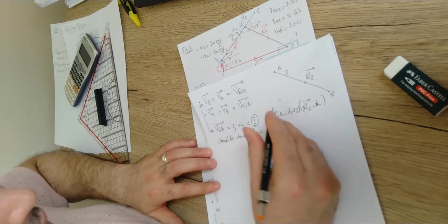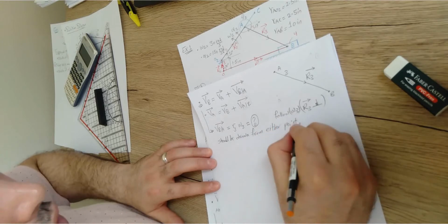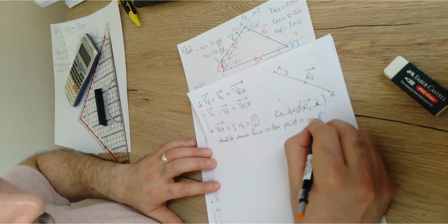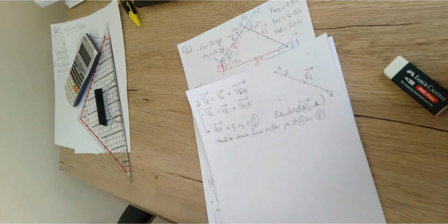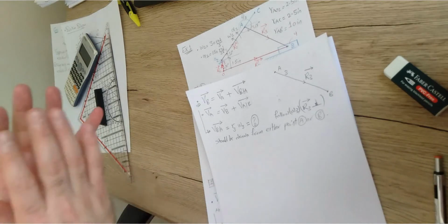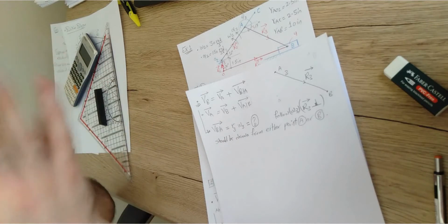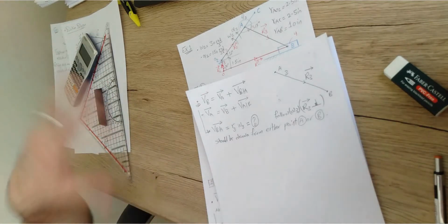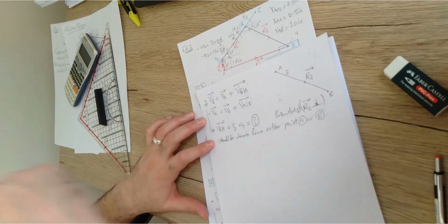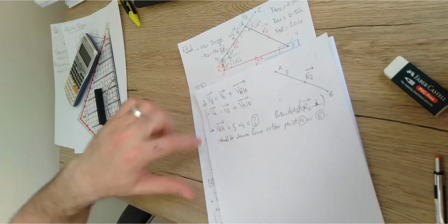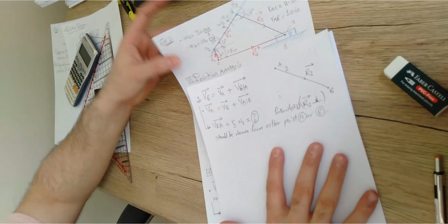Also, you should understand that this one should be drawn from either point A or point B, depending on which one of these 2 points will be located first in the velocity diagram. As I said, we start from the link that is fully defined, where the velocity information is already given. Once we finish this link, some more points will start to show up. If one of these points is point A, I'm going to start drawing this one from point A. If it is point B, I'm going to start drawing this velocity vector from point B, as I'm going to show you. Make sense? This is the second case, and this is for the next link.